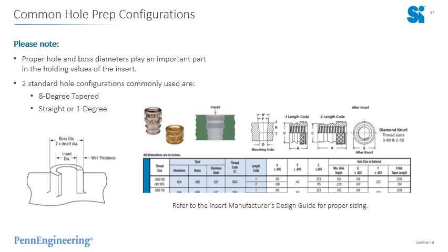Common hole prep configurations. As I've said throughout this presentation, you do need to pre-drill or pre-mold a hole before installation, and in doing so you're often posed with dimensions. The dimensions needed for a hole can be found in our catalog. Just keep in mind these are recommended hole depth and hole diameter dimensions.